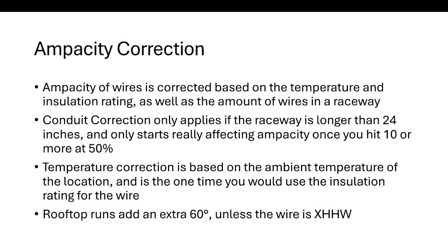Rooftop runs of wire add an extra 60 degrees unless the wire is XHHW. I don't think it applies to XHHW-2 or W-2. I think it's just the XHHW.